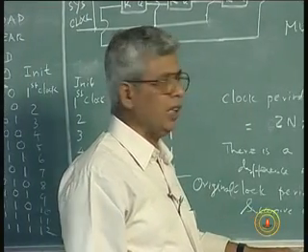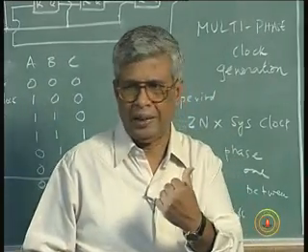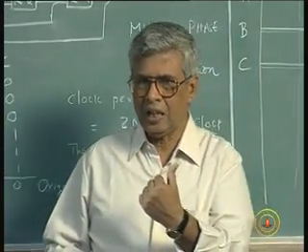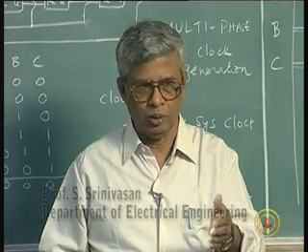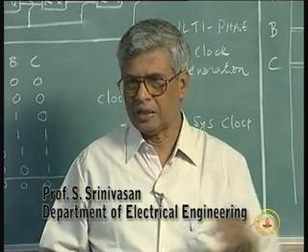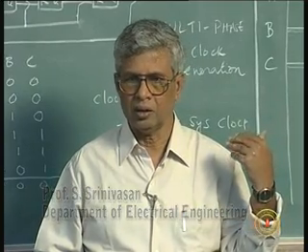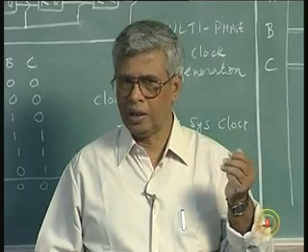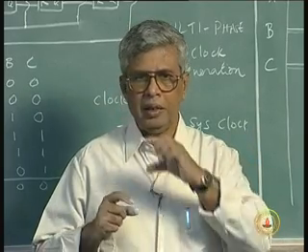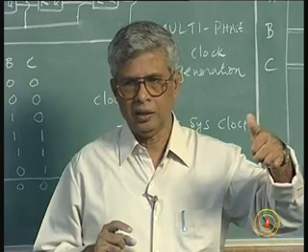Such a, this is also called a counter. See, counter is basically what to do in a counter. Counter, you give a clock pulse, divide that clock by a factor of 2 by every flip flop, frequency is divided by 2 in every flip flop stage. So, same similar thing here. So, this is also a counter, but the only thing is the output of this counter we twist and then connect it.